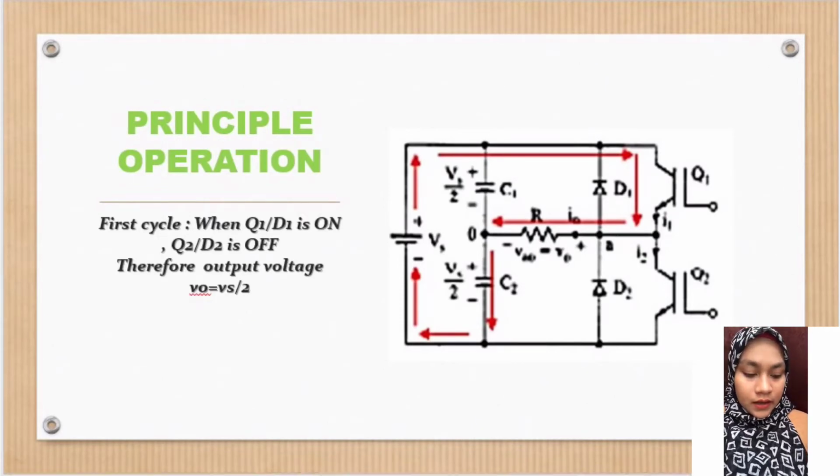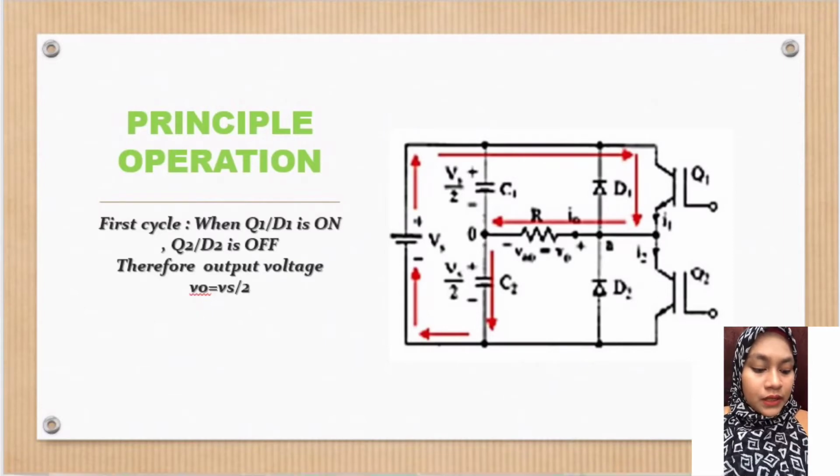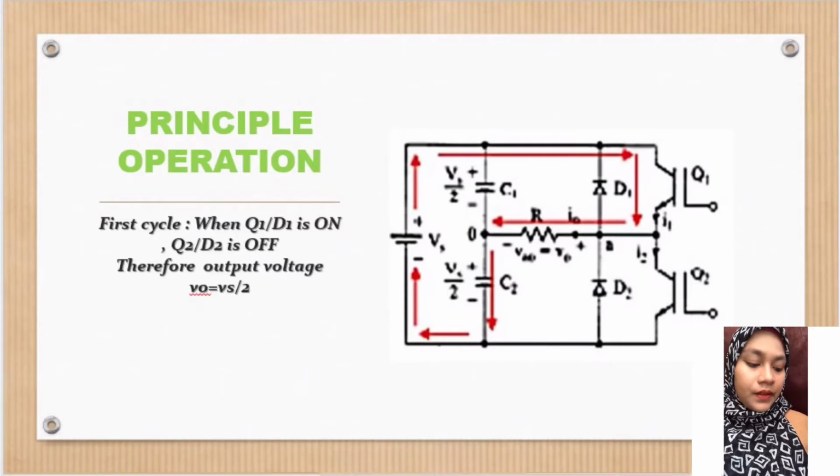Also, there are two kinds of three-phase to single-phase CCV. The first type has a half-wave rectifier for both the positive and negative bridge, and the second type has a full-wave rectifier as shown above. The first type is not used often because of its poor efficiency.